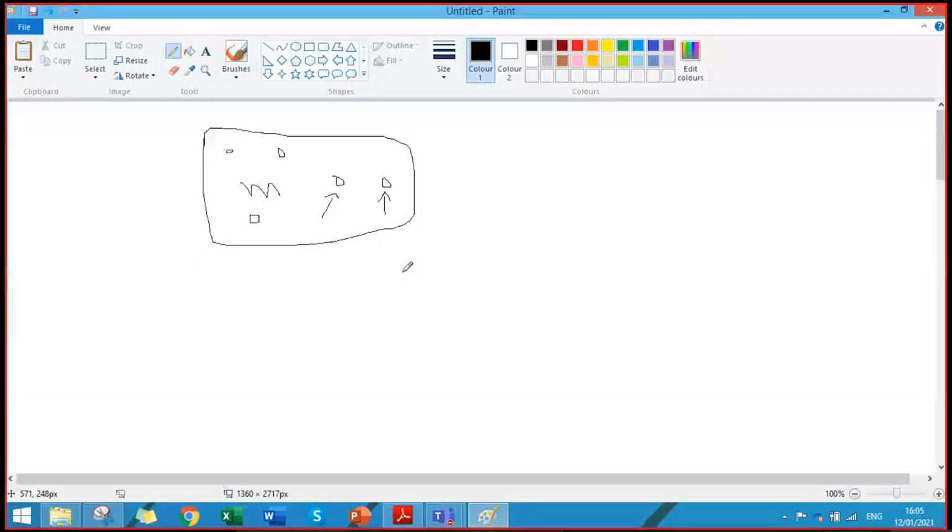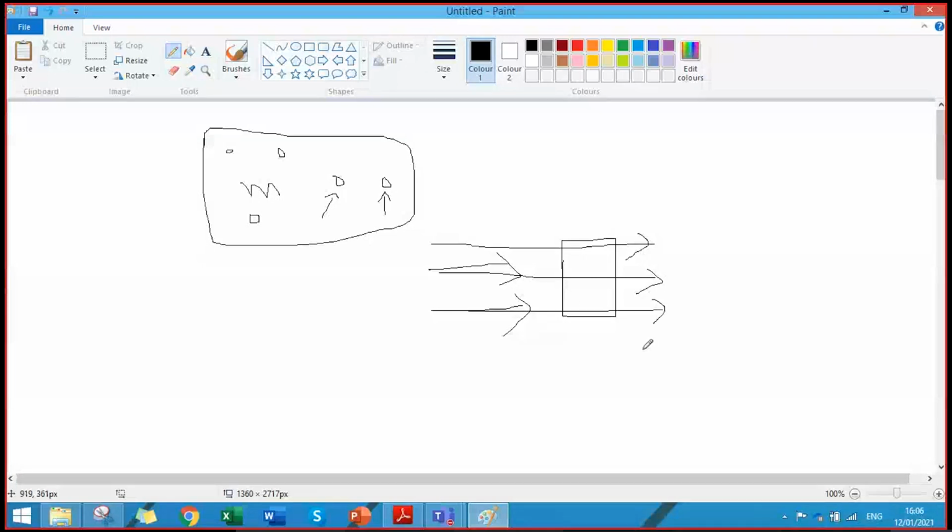Let's say this is a body and air is passing across it. We are interested in seeing the effect of the air passing over this body, the force that this air will exert on this body, right? So there will always be a different mass of air passing across this body, with different properties. So we cannot use the system approach. We cannot define, okay, we are taking this mass of air and we'll see how it interacts with this. No, we are having fresh air every time.